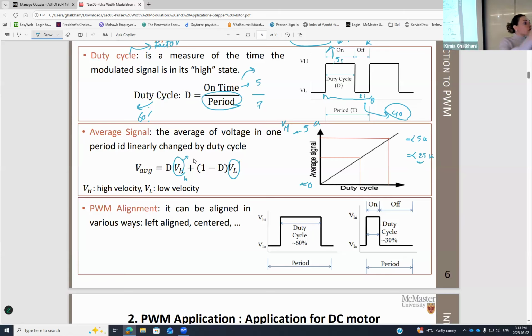If there is no BMS, you can come down. You can just discharge the battery to less than 2.5 volts. But if you do so, you are going to kill the battery, because what you do impacts the chemical reaction between the cathode, the anode, and the electrolyte, and it will ruin it. Therefore, always look at the data sheet for any electronic devices.